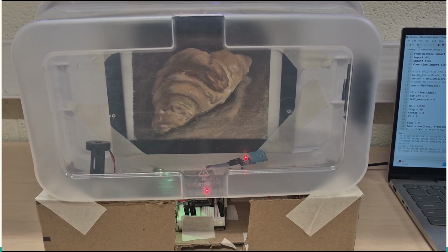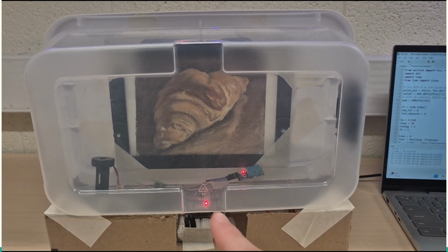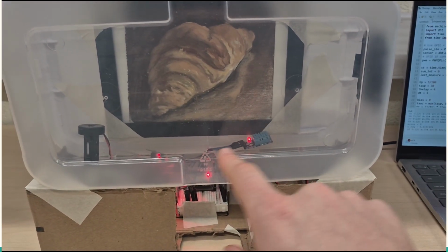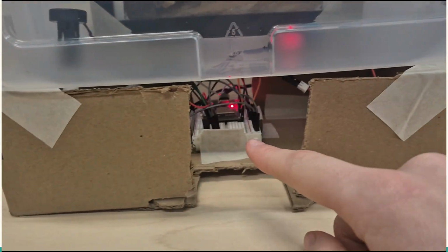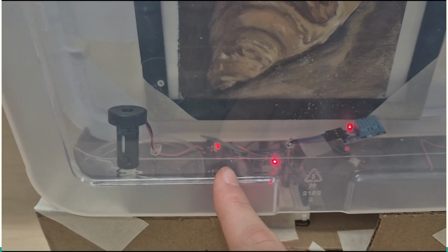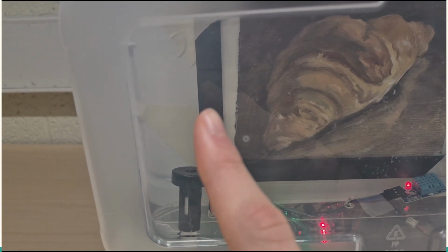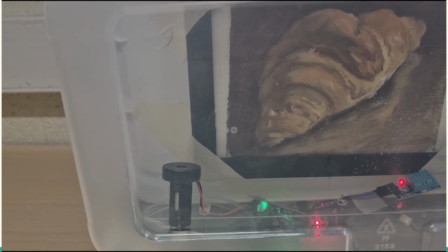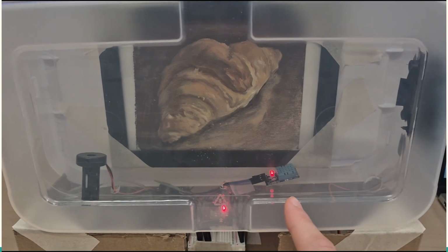Here is our brief overview of our process control project apparatus, including an enclosure, an example painting, humidity sensor, humidifier, a fan, and ESP32 microcontroller. When this light turns on, the humidifier begins to output. It's hard to see. You can kind of see in the black background, but it's hard to see on camera. But that is being controlled based on what this humidity sensor is sensing.